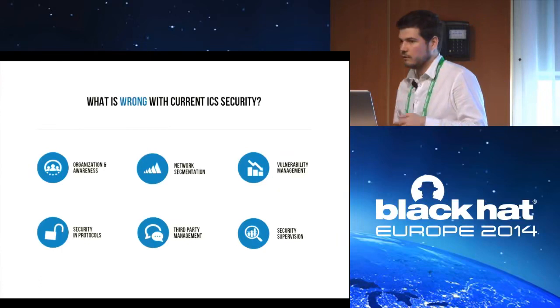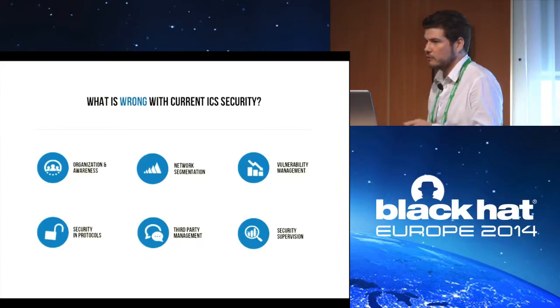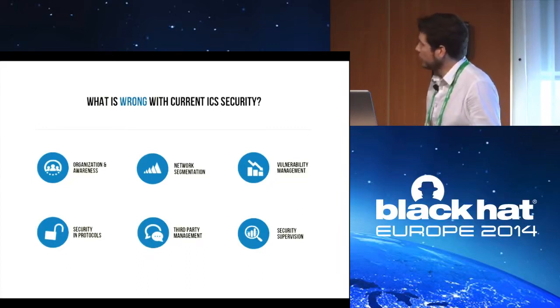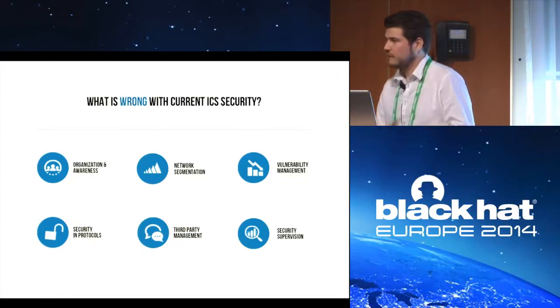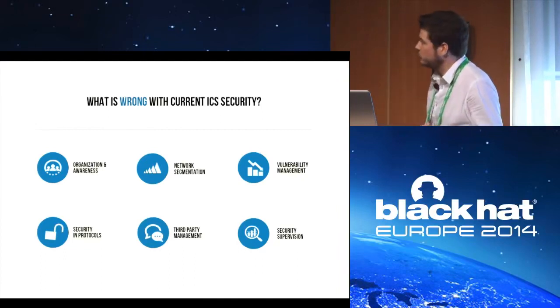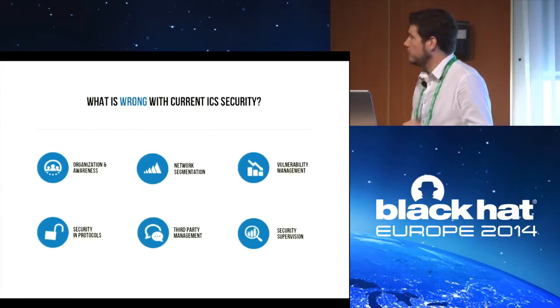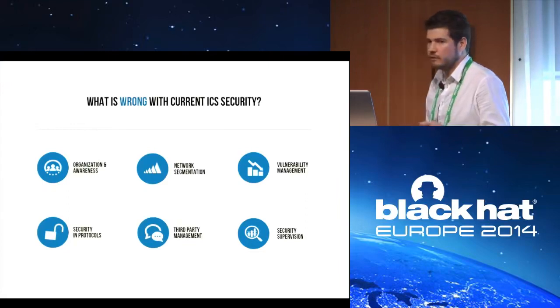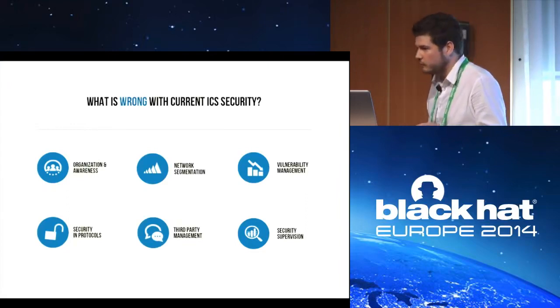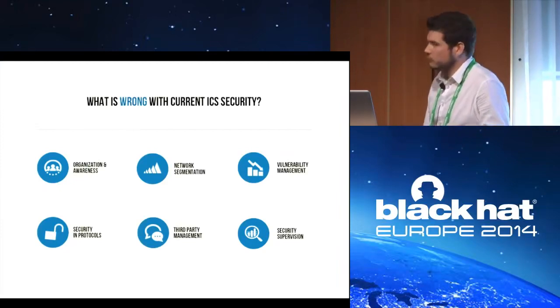Most of the time they run 24/7, so it's not possible to apply the patch during the night as we can do in the corporate network. So yes, patches are published but rarely applied. If we talk about classical IT components like Windows XP or Windows 7 workstations, since the ICS is not directly connected to the corporate network, you do not benefit from WSUS systems, for example. So even the Windows machines are mostly not patched.